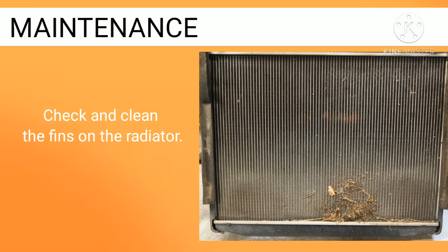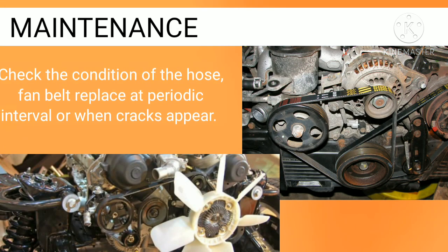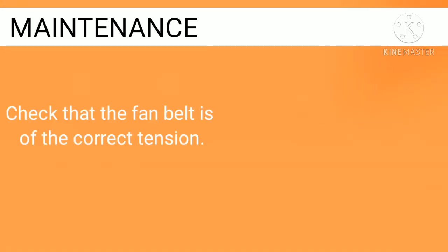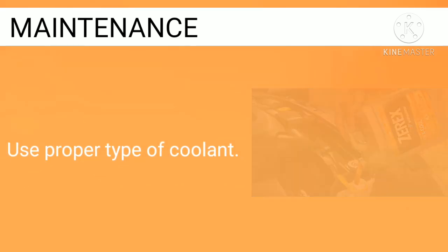Check and clean the fins on the radiator. Check the condition of the hose, fan belt. Replace at periodic interval or when cracks appear. Check that the fan belt is of the correct tension. Use proper type of coolant.